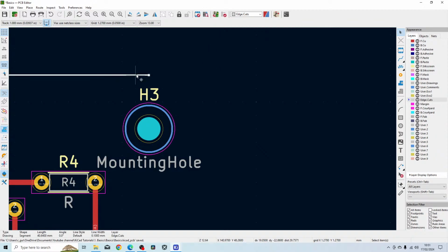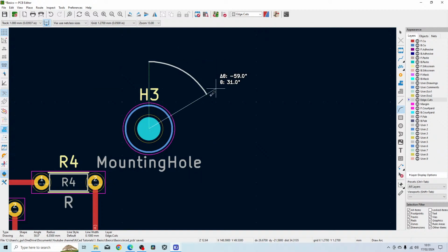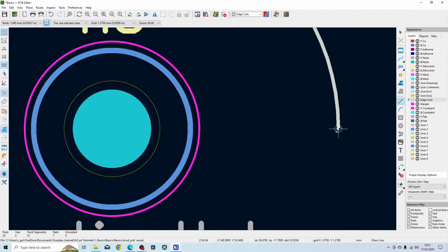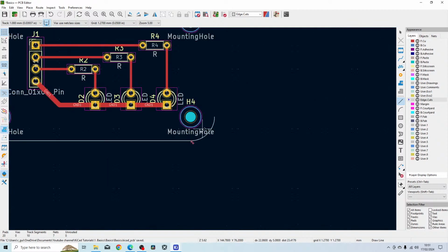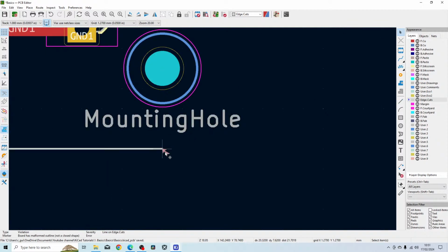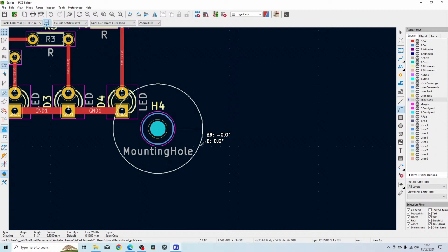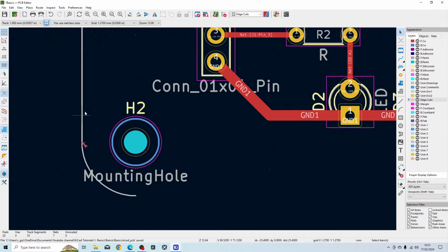Delete that. What I'm going to do first is make the 90-degree track. Okay, so I've got the edge outline over there. Change that to 0.1, sorry, and then connect up the track from there. So let's try doing that. I mostly use Altium, so I'm still learning here and trying to show as much as I can.